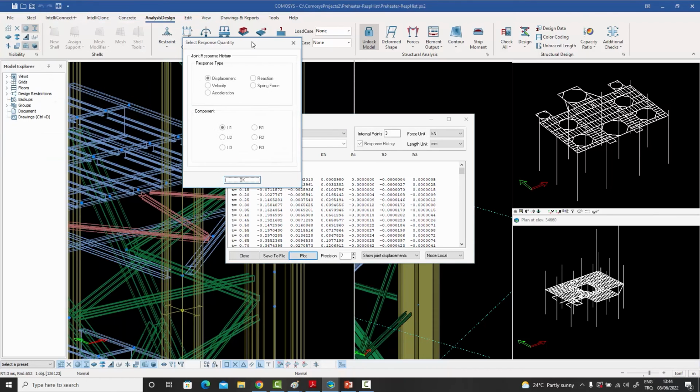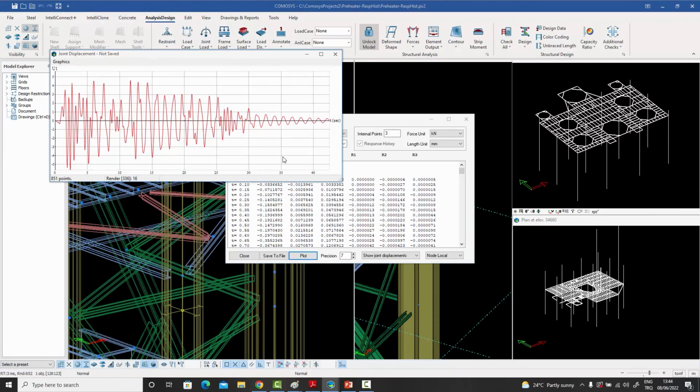And this time when we plot it, we will see it's a more violent shaking actually, because over here it's much stiffer near the base, and the higher frequencies, the smaller periods, play more of a role, but the overall amount of displacement is much smaller than the top floor, because it's very close to the ground floor.